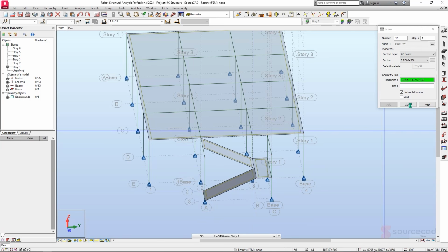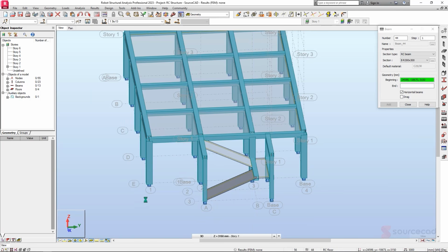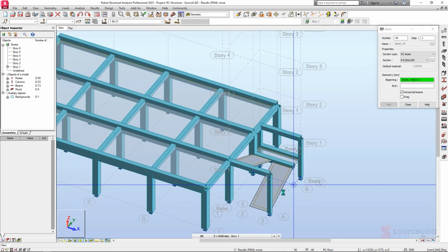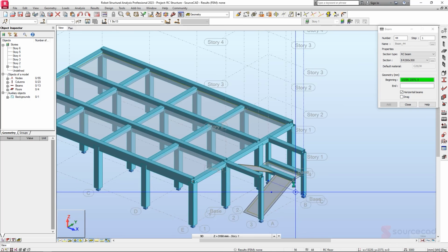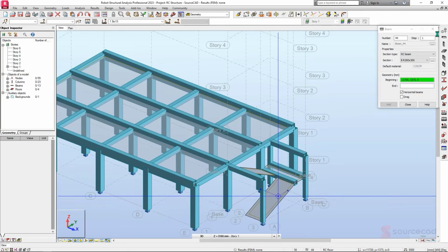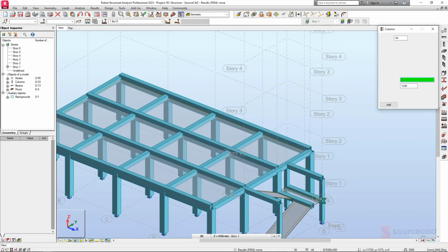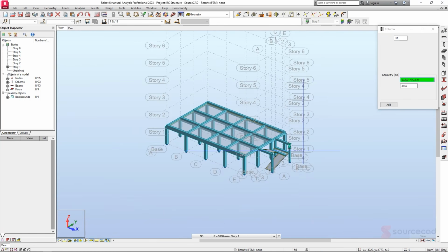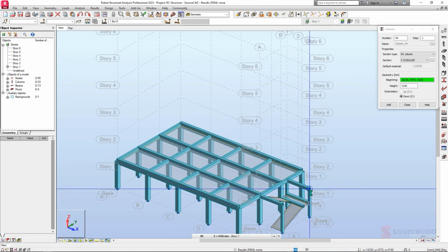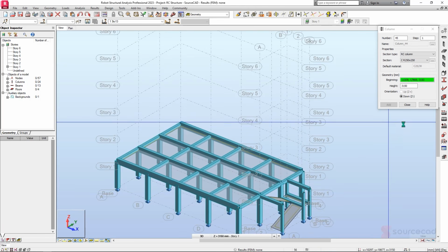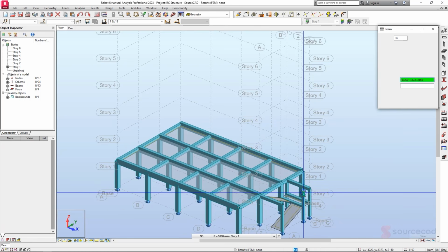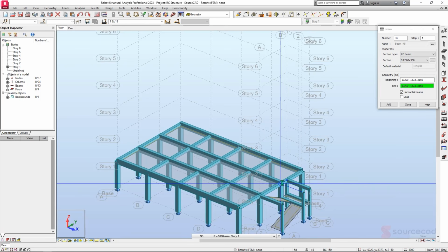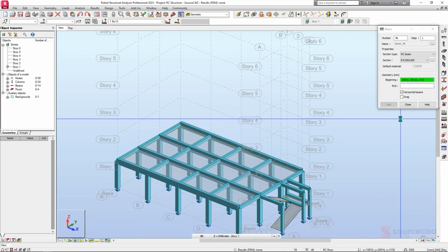And that's the way it's actually done. So if I was to turn on my section shape, just to confirm that everything is alright, everything looks good, just that one column is missing here, so as to carry the weight of this specific beam. So take your column, we want it to be down. So from this point, just like that, we now have our column and place our last beam from this point to that point, just like that.